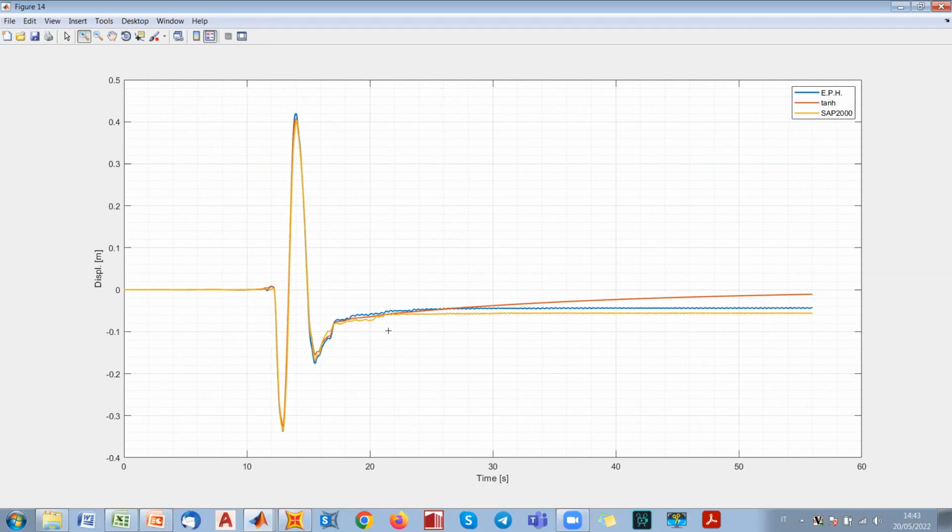And then for the residual displacement, you see that, okay, we get close to zero, but you see what I meant yesterday, according to the hyperbolic tangent. The hyperbolic tangent is generally associated to zero frictional force when we have zero velocity. So what we have is actually a continuous and continuously applied restoring force to the device and generally to the system, with no frictional resistance.